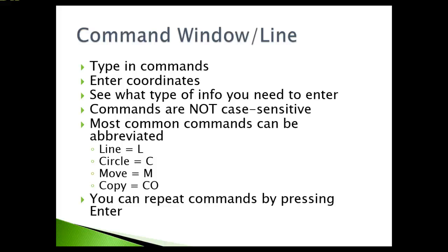Everything that you type in there is not case sensitive. Most things are not. And you can also abbreviate some commands, like line. Instead of typing out L-I-N-E, you can just type in L. Circle is a C, M is move, CO is copy. You can also repeat commands just by pressing enter. Anytime that you want to get rid of anything that's in your command line, you can press the escape button, which is the upper left hand corner of your keyboard, the ESC for escape,